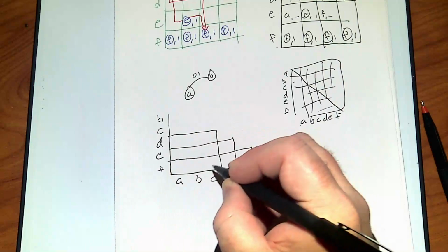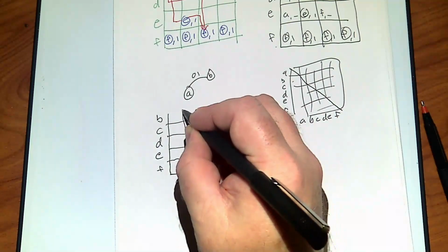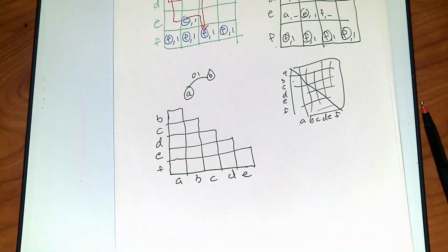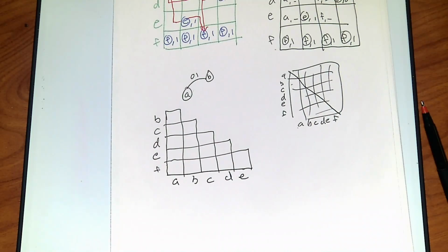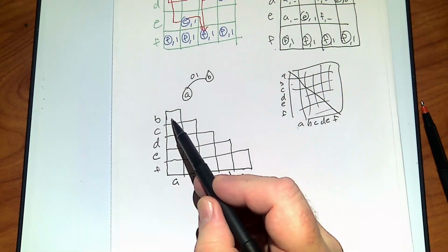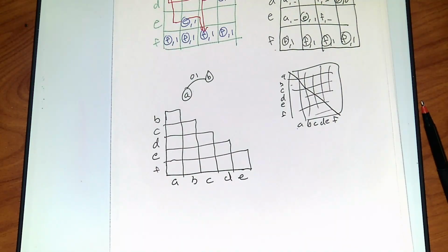So now I'm going to formally draw all of those lovely little boxes because this is that lower part. This just lists everything I need to check. That's all of this chart. This is a very standard looking chart. If you look at any book that does state reduction in digital logic, they all do this chart. What I'm going to do is put a check mark if they are compatible. I will put an X if they're not compatible. And if I don't know this one, I'll write all the conditions necessary to make them compatible.